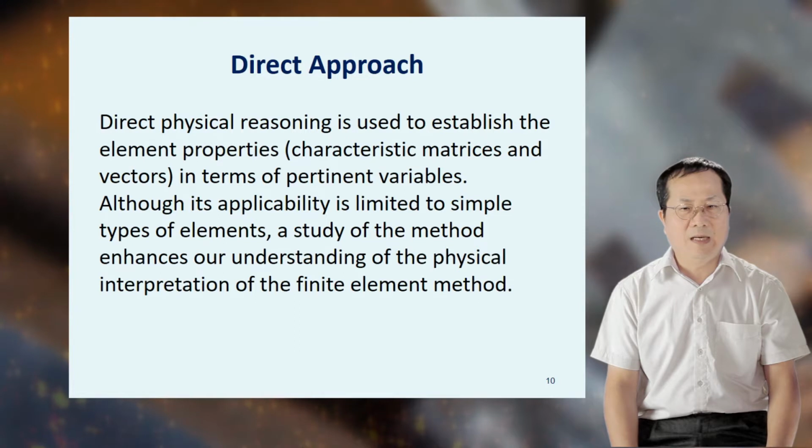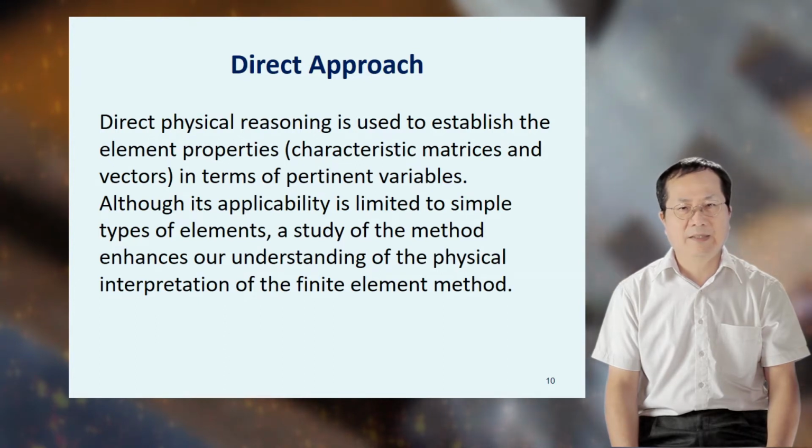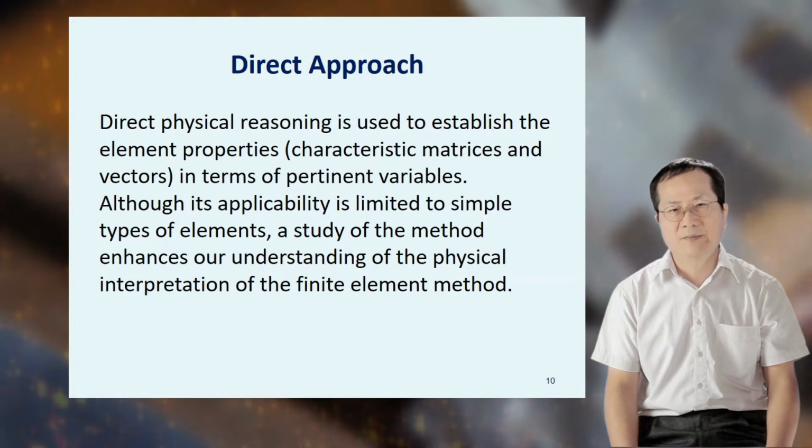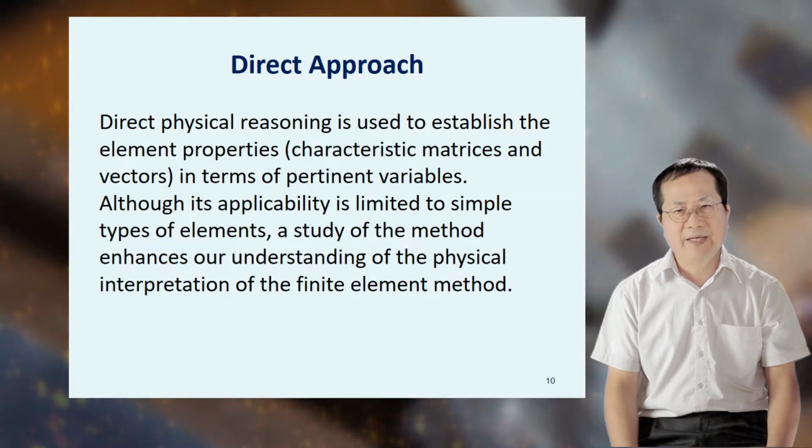For the direct approach, direct physical reasoning is used to establish element properties like characteristic matrices and vectors in terms of nodal variables. Although its applicability is limited to simple types of elements, a study of this method enhances our understanding of the physical interpretation of the finite element method.